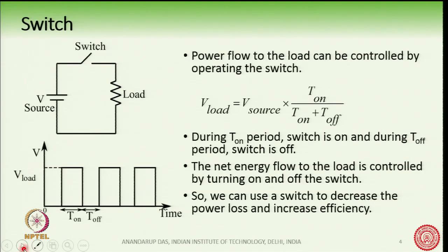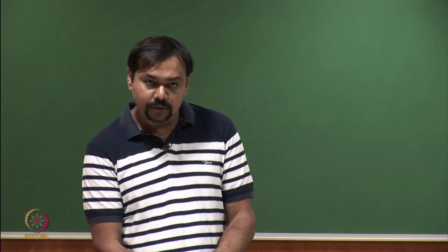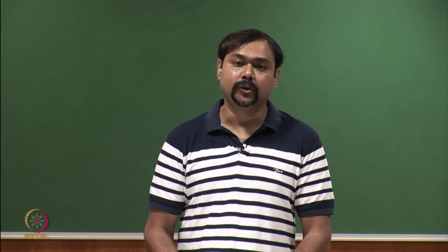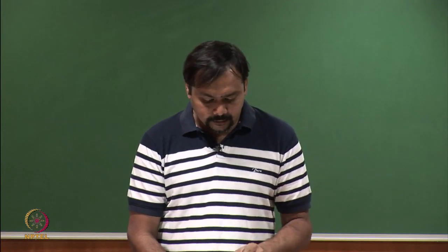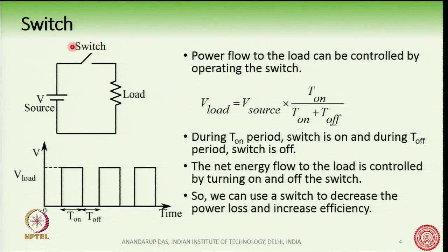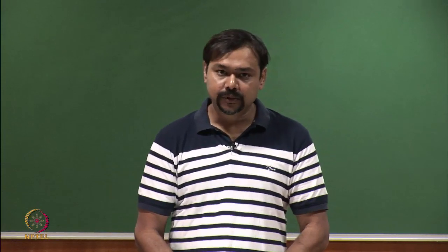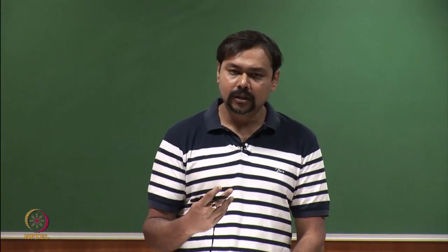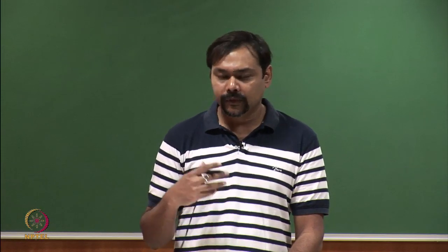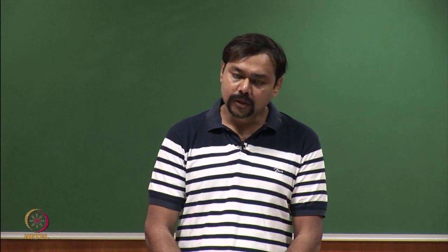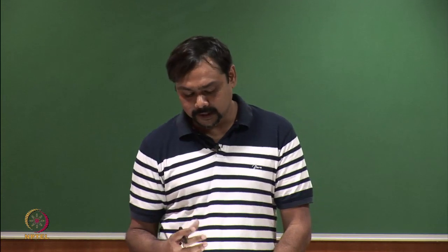So, what is the solution for this? The solution for this is to use a switch, which I have shown here. This is the switch here. Now, when you connect the switch, suppose this is an ideal switch, I mean it does not dissipate any heat. And it is a fully controllable switch, which means I can turn it on and I can turn it off with control signals, which is totally controlled by me.